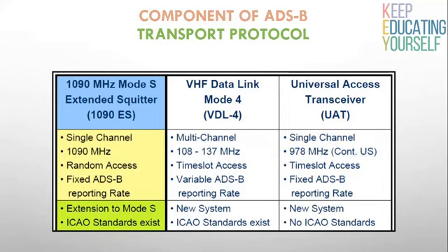To enable an aircraft to send an extended squitter message, the transponder is modified. An aircraft position and other status information is routed to the transponder. ATC ground stations and traffic collision avoidance system equipped aircraft already have the necessary 1090 MHz receivers to receive these signals and would only require enhancements to accept and process the additional extended squitter information.